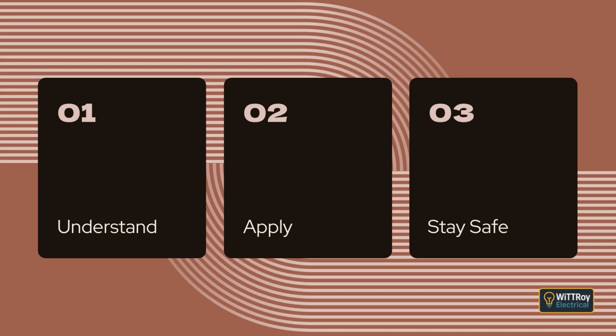Switchboards inside areas used for sanitizing or hosing down must have an enclosure with at least IP6X protection. Switchboards must not be installed where people need to pass during an emergency exit. Smoke from a fault inside the switchboard could block escape routes. Switchboards must not be installed in cupboard spaces that contain fire hose reels.